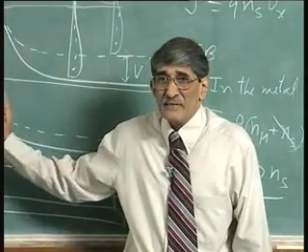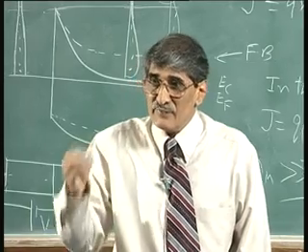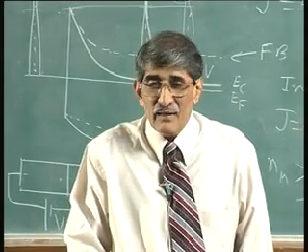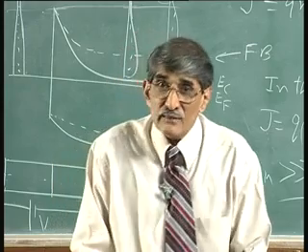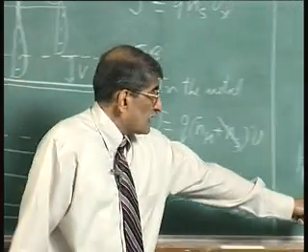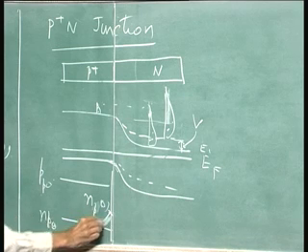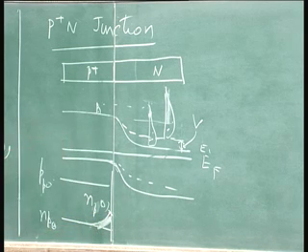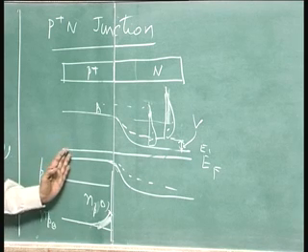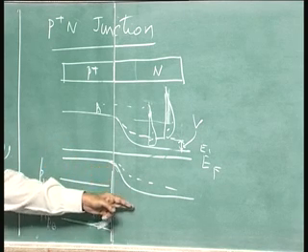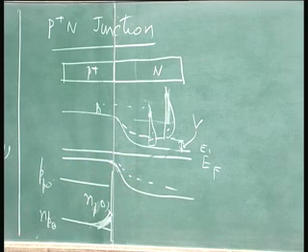Here it is taken away by drift in the presence of large quantities of electrons, that is why it is fast. And in the other case it is taken away by diffusion, and notice you have this charge storage effect. This is the charge that is stored here. Similarly, on the other side you can talk of holes, the same thing. Holes are hitting the surface at a fast rate, but they are taken away at a small rate, because the hole concentration in the N region is very small.